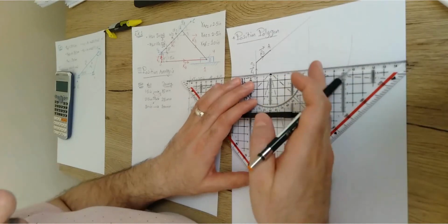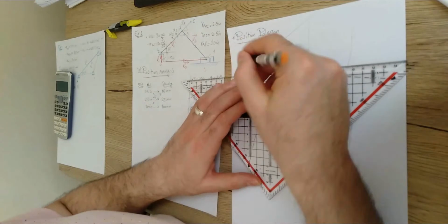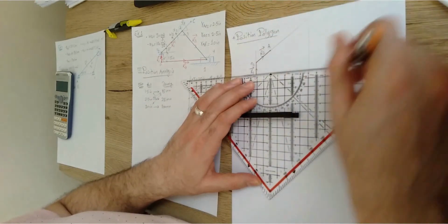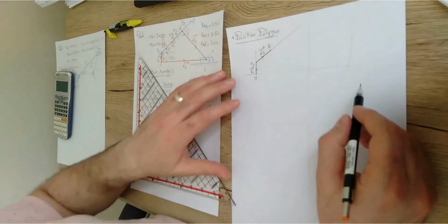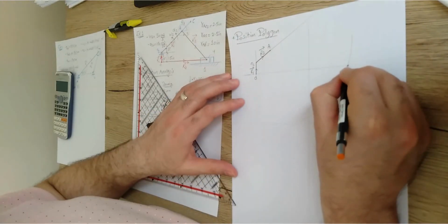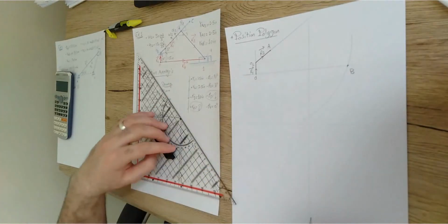Make sure that you align one of these vertical lines of the triangle with your reference vertical line. Then draw a very light line. So I measure the angle, then I draw a line. This second line should be a locus. So this is one locus, this is the second locus. These 2 loci should intersect at a point. This point will definitely be point B that we're seeking, right?